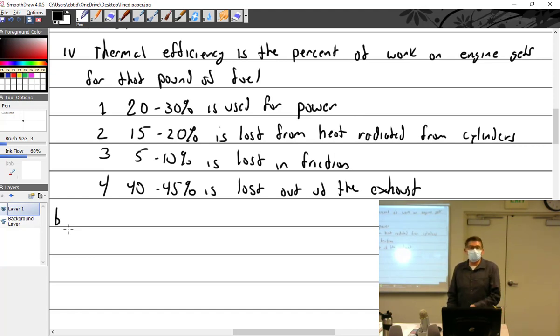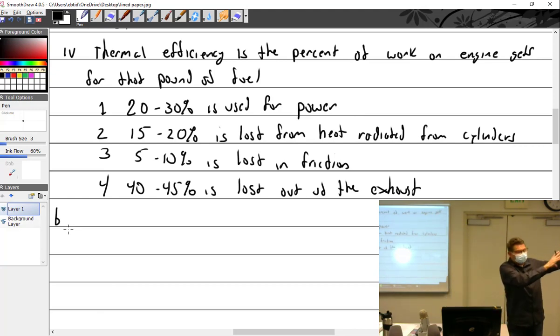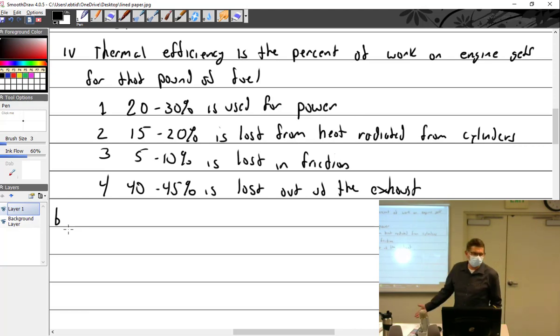It's only called low lead in comparison to the extreme lead fuel they used to have. Our 100 low lead has something like 4 times the amount of lead ever put into the most leaded car gas ever used. So it is a tremendous amount of lead, and it creates problems not only for the environment, but if you don't care about that, it actually creates problems for the aircraft engine itself.